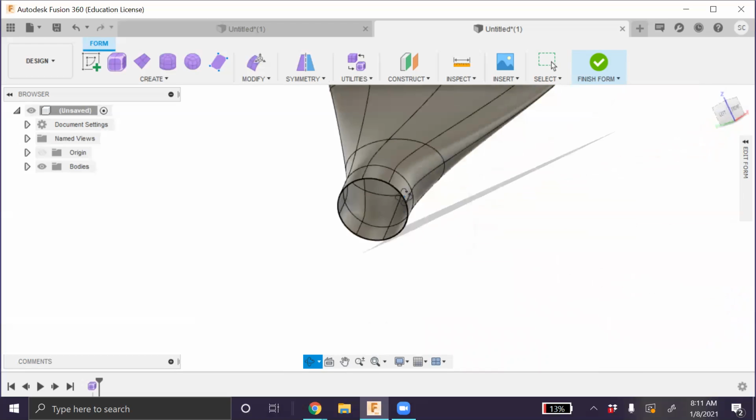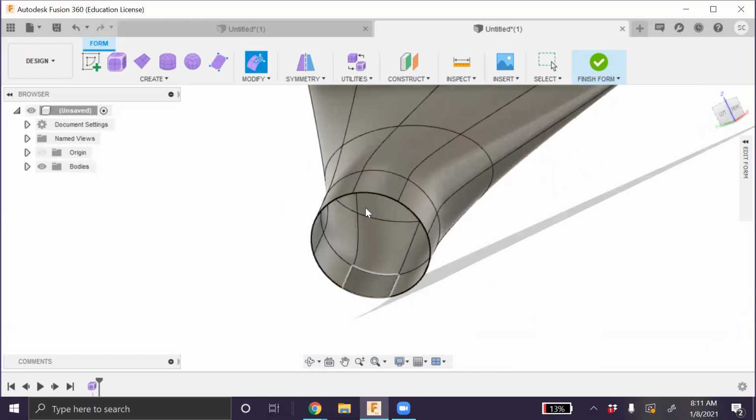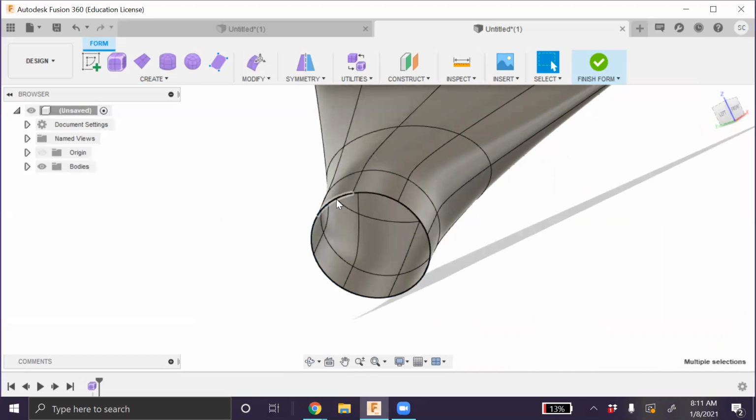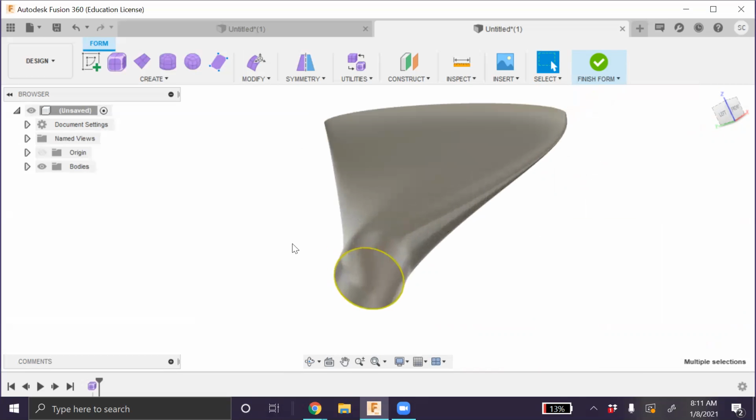Now let's go ahead and look at the other end. Free orbit, turn around. Let's look at it. We need a shaft, we need a coupler kind of entry over here, which will sit with the shaft. Same thing, press here, press shift and double click. This should select all the faces. I'm sorry. It did not get selected before because we had some selections over here, so you're confusing the software basically.